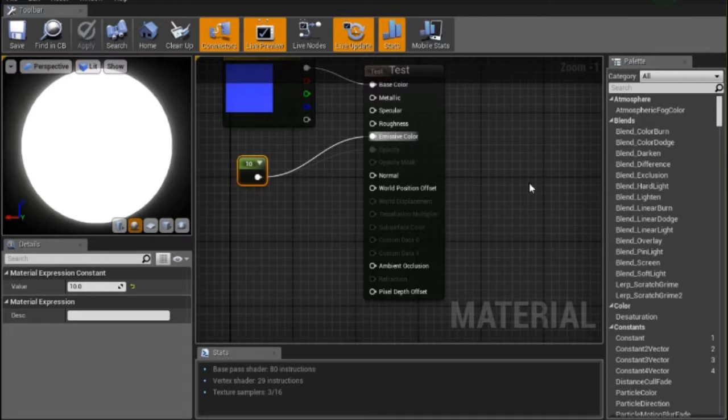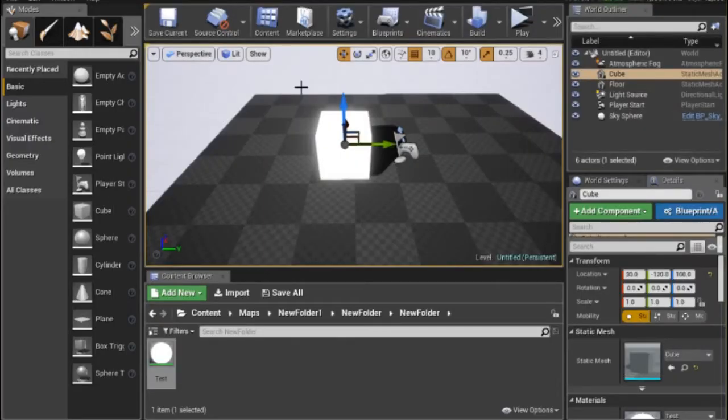Before we start with that, I want to make one small correction from part 1 and give you additional information. First, the correction: you can go higher than 1 with the value for emissive colors, and then you get a much brighter light if you go higher with the number. However, with roughness and so on, you won't change much by going higher than 1.